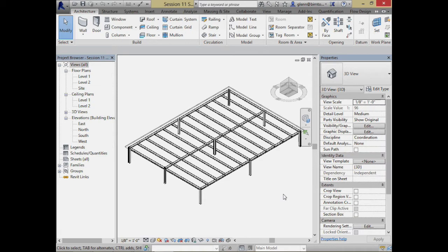What we need to start with is these structural elements. I've got some beams, I've got some floors. It's doing pretty good. There are 2 basic things we need to do. One is boundary conditions. Boundary conditions is the notion that those columns are going to rest on something. And in order to have the building not move in space, we have to say something about how it's grounded. It could be grounded with fixed connections, or pinned connections, or moment-resisting connections. There are all these different connections we might apply there. It's quite important, because the type of connection you assume says a lot about how the stresses are resisted by the building.